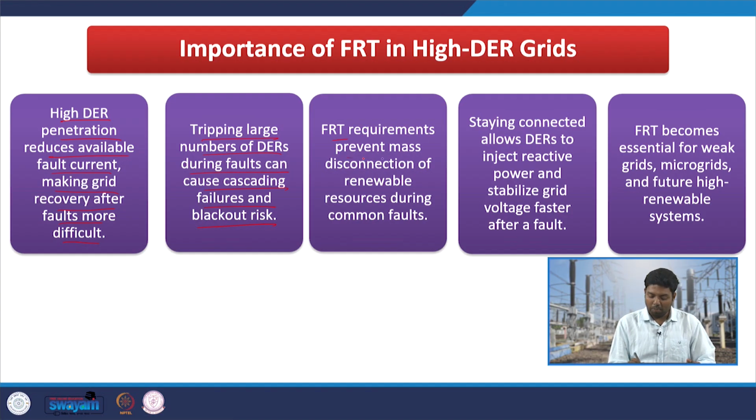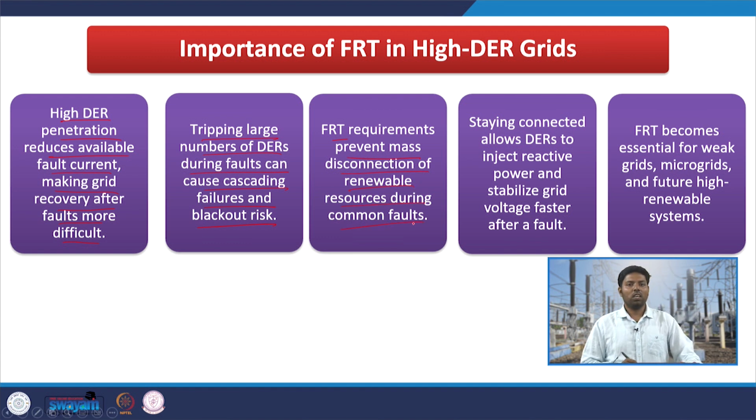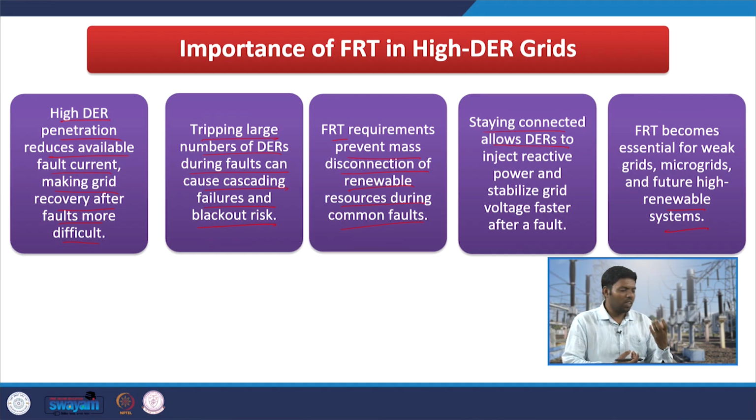FRT requirements prevent mass disconnection of renewable resources during common fault conditions. Staying connected allows DERs to inject reactive power and stabilize the grid voltage faster after a fault, as we just discussed. So, fault ride through becomes essential for weak grids, microgrids and future high renewable energy systems, because whenever you have a weak grid, the voltage level is already not able to be maintained.